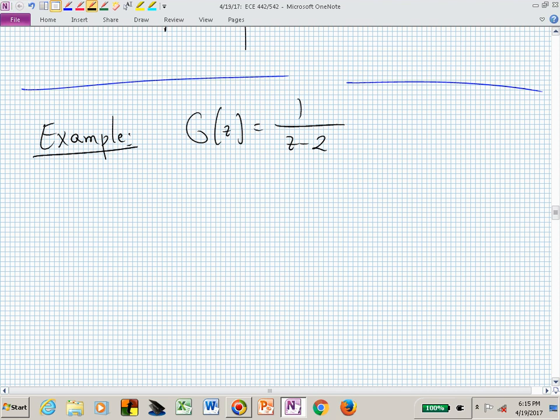If you implemented a proportional controller, what do you know might happen with respect to steady state accuracy? If I put in a 4, will you reach 4 with a proportional gain? Can you see the root locus of this with a proportional controller?